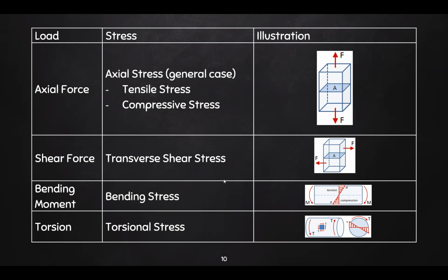Next, you have your shear force, which creates transverse shear stress. Once again, we have this cross-sectional area. We have our forces parallel to it. Next, we have our bending moment, which creates bending stress. So bending moment, same as moment. If your moment is like this, okay,